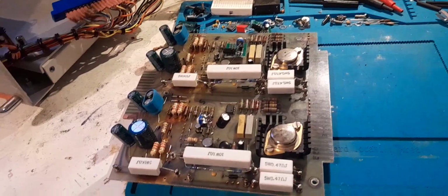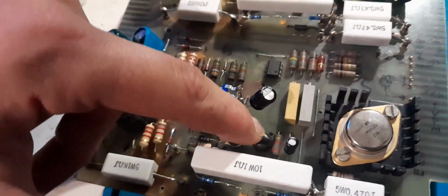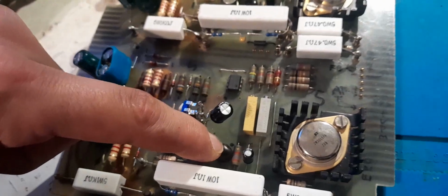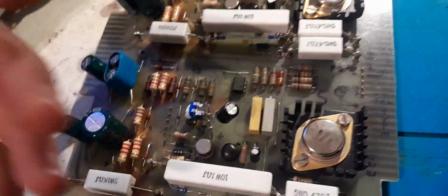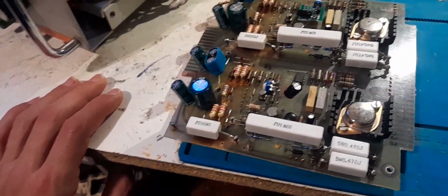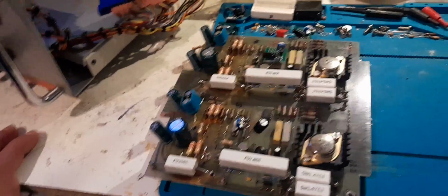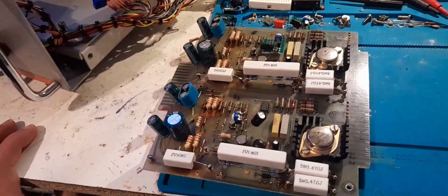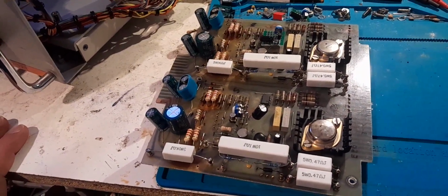And then I was just thinking about this, the transistor that's been replaced has been replaced from a 60 volt part to an 80 volt part, incidentally on the slave channel. The slave channel was the one that, when I got this, had the 20k pot where the 10k voltage set pot should have been, and you could turn it up to 55 volts. Now I'm wondering, did someone actually modify this thing so that one channel went up to 60 volts and one channel went up to 30? It kind of makes sense because of where it came from.